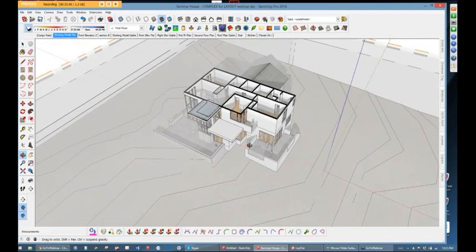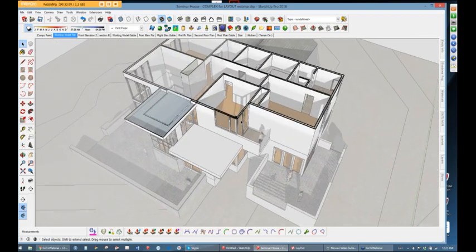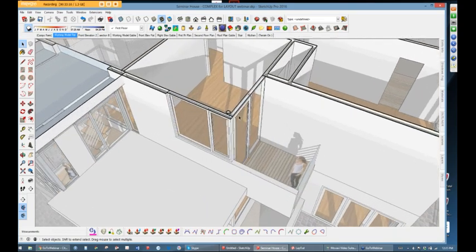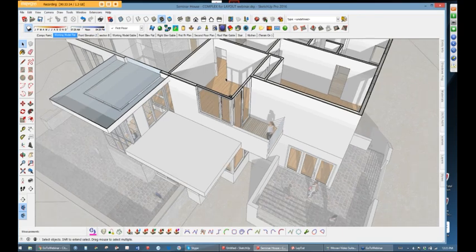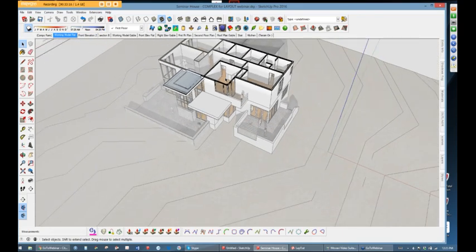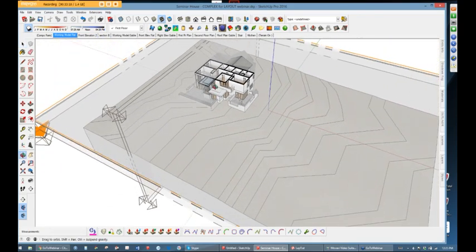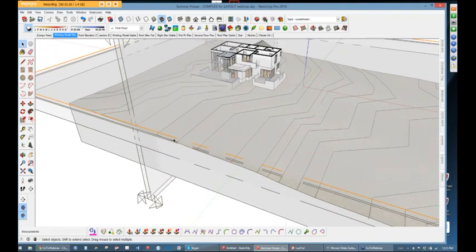And you can see what's happened as I've cut through the walls. I'm a little bit high because this is not what I want. I want to be able to see those windows cut. And I think, in a typical drawing that you might do, as we've all been taught, a section should be cut about 4 feet above the floor. So select the one you just put in, and it's going to be the orange one. Use the move tool and drag this down.